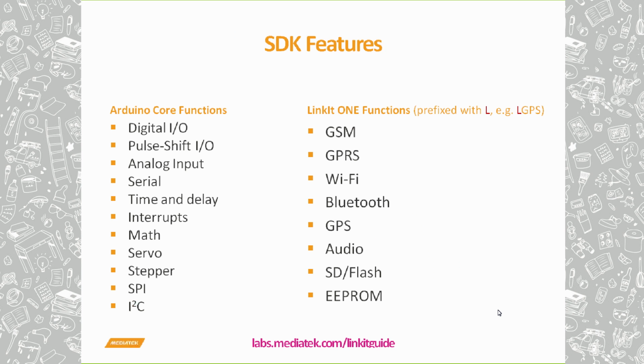So the features: we support all the core Arduino features, so nothing less, but we added a lot of functionality because we have a lot of additional chips that make the board so great. We have the GSM module, which gives you access to sending and receiving text messages and creating and receiving phone calls. We have GPRS, which gives you TCP and UDP socket functionality. The same goes for Wi-Fi. With Bluetooth, we support serial port profile and GATT.